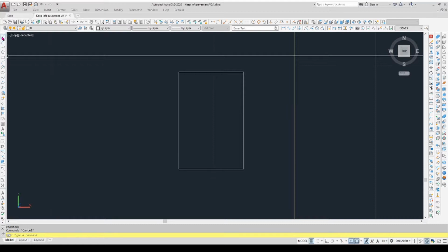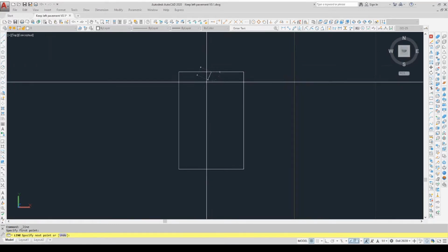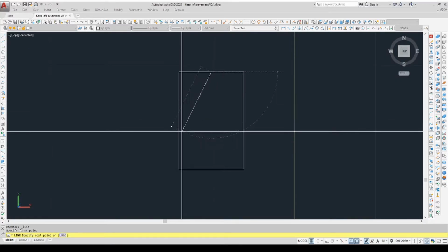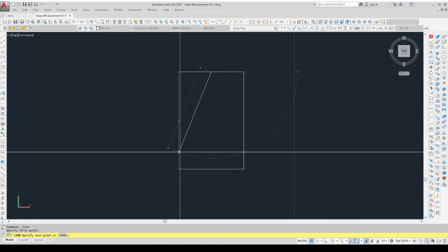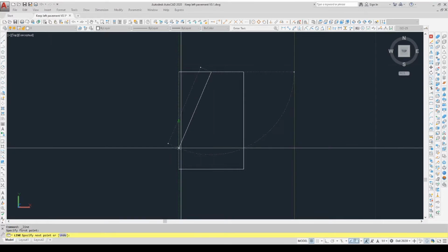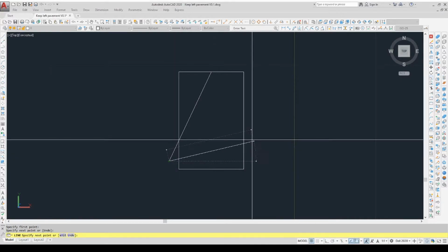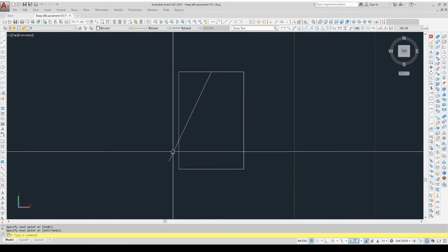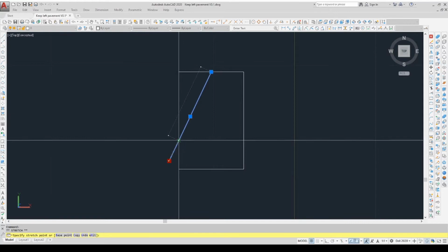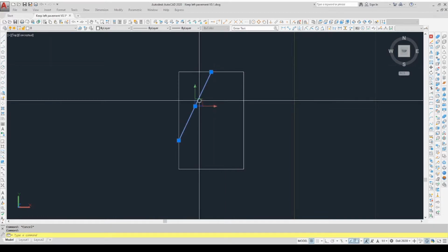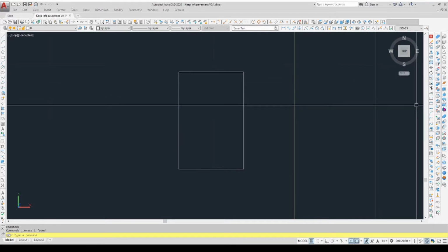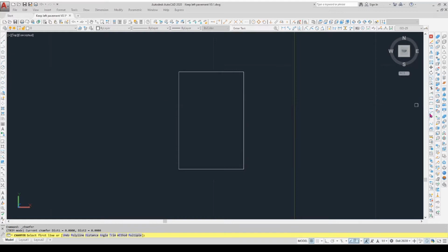So we could try and draw a line. I can pick the middle point, but it's not going to let me select anything other than the midpoint, and that's not sharp enough. I want to be somewhere down here, and I could do it by freehand and get it to lock onto the line. Do that for you now. So I can grab that and I can move it back, and it finds the intersection point and produces the line that way. Or I can actually make a chamfer, he said confidently.